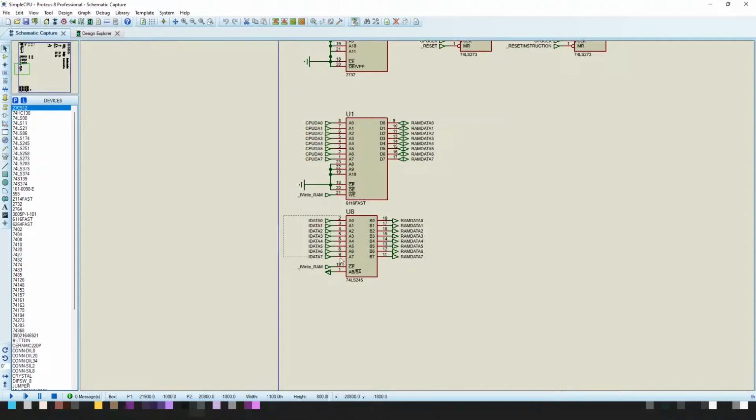And the internal data bus, basically the value that is asserted or selected from the select logic for the internal data, is optionally, when the RAM is being written, passed through. This is again the low chip enable, and the data direction here is set to be high. So high logic means from A to B. AB means A to B. So only when we are trying to write RAM, we take the data on the internal data bus and we pass it through and we present it to the RAM data internally.